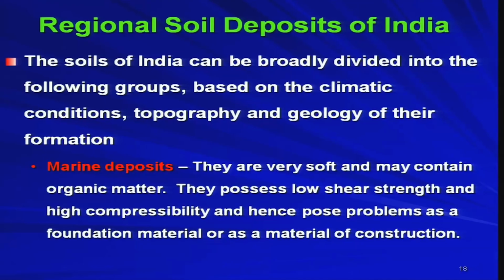If the soil material has very high compressibility, then it should not be a very good material for construction, and hence poses problems as a foundation material. That is very true, because if you try to place the foundation on top of this kind of marine deposit, what will happen? Because of its softness the foundation may settle down excessively, due to its compressibility it will settle down, and due to its low shear strength you will get failure.